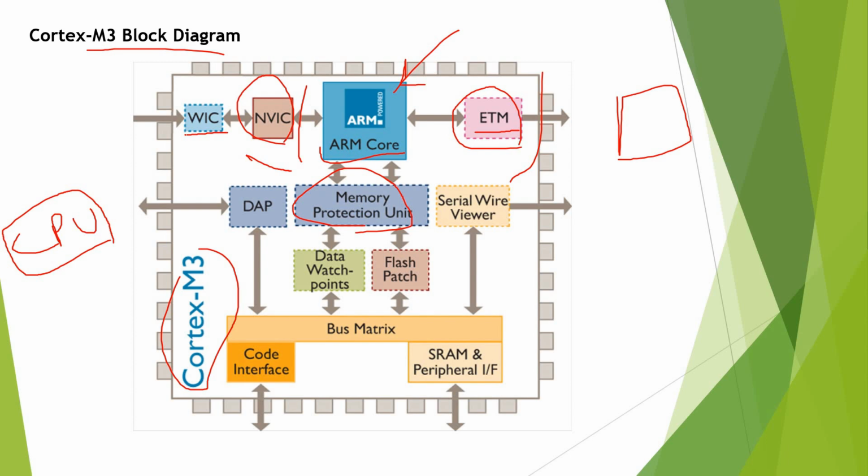And at a certain moment, we need to wake up our core from this low power mode. Therefore, especially for this deep sleep mode, ARM provided a dedicated block called the wake up interrupt controller. This block offers an optimal way to handle the different signals coming from the system on chip or from the external system connected to the Cortex-M3 to wake up the core from deep sleep mode, like prioritizing which signal should wake up the core first, defining the edge of these signals, and many other optional functionalities.